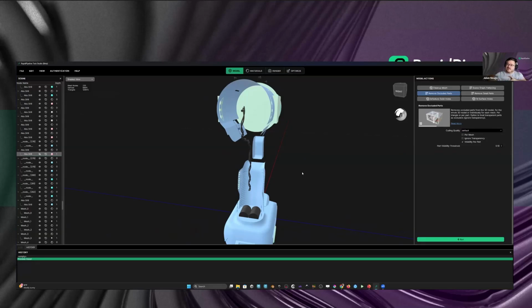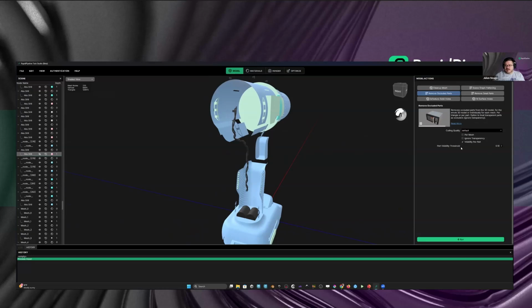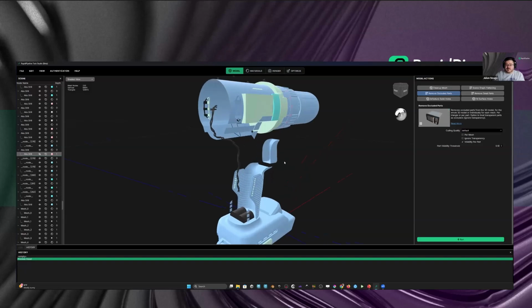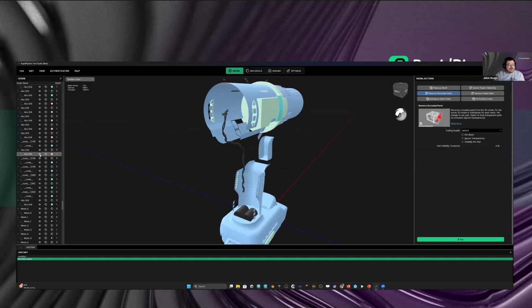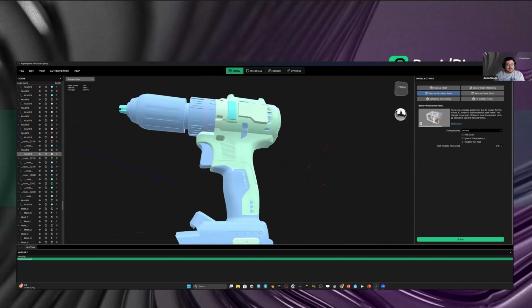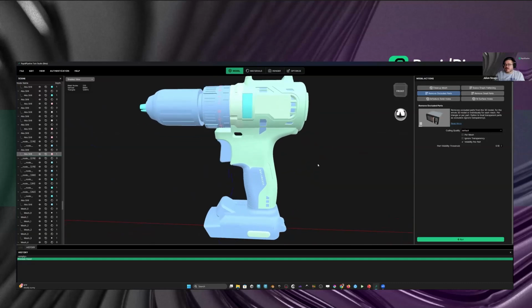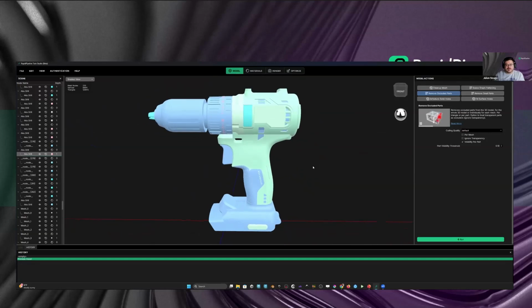You can actually manage to remove these by playing around a bit with the culling quality and the visibility threshold, right? So if you say, hey, all triangles of this cable were maybe visible to, let's say, only maybe 20%, then changing your visibility threshold usually covers that as well. But yeah, usually this is the correct way, and you don't necessarily want to cull things which are in any case somehow visible. But again, you can always adjust that and remove more or less of the parts as well.